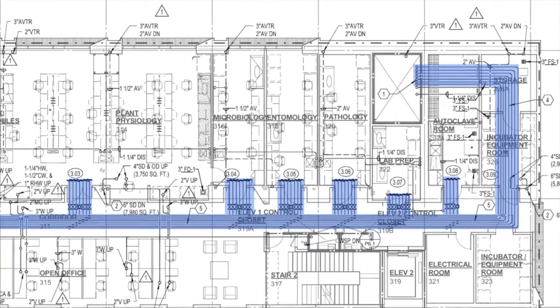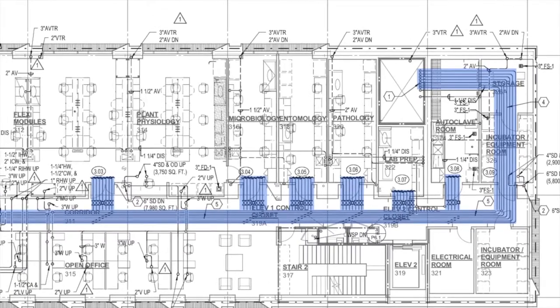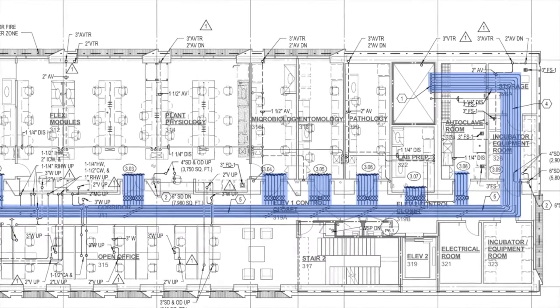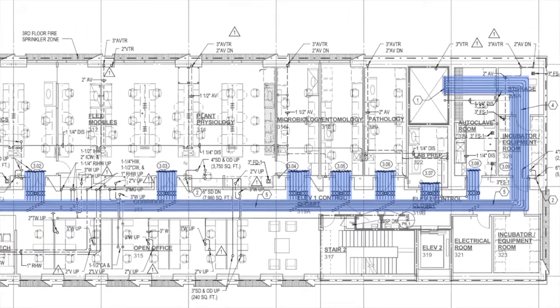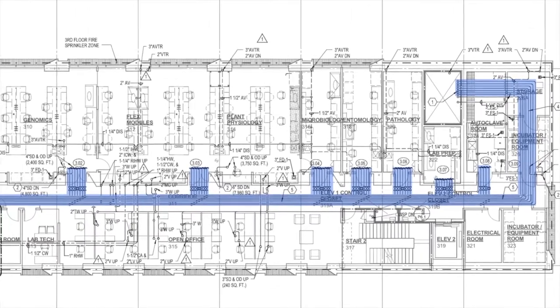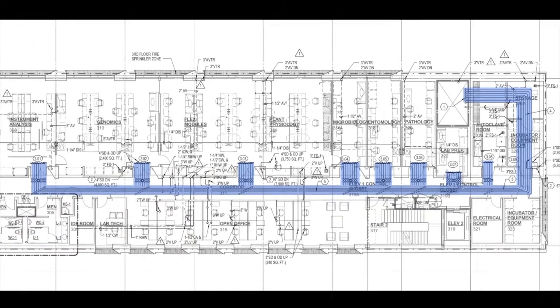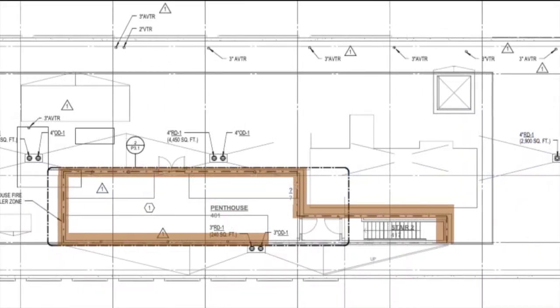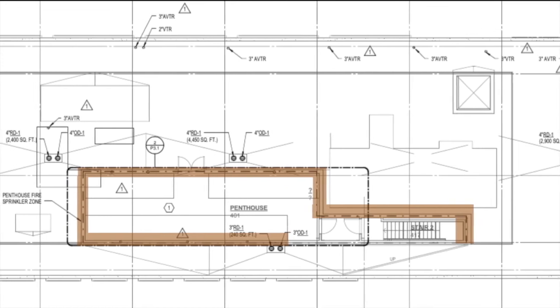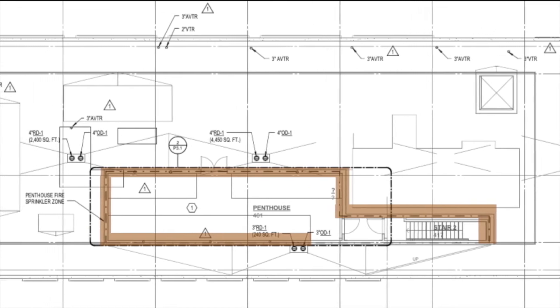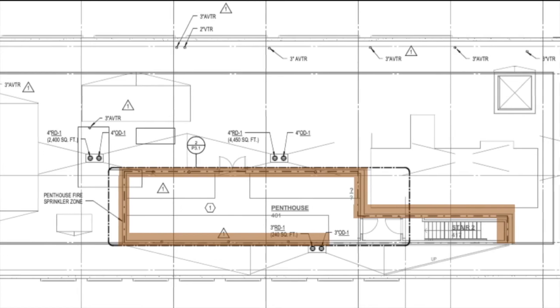The third and final floor with major rough plumbing requirements has been broken up into 8 major outlets, leaving the mechanical room. Each of these 8 rooms will receive 2 hot water, 2 cold water, a ventilation, and an acid waste pipe from the mechanical room. Penthouse has some plumbing requirements highlighted in brown, but are considered minor and are mostly for fire sprinklers. These will not be considered.